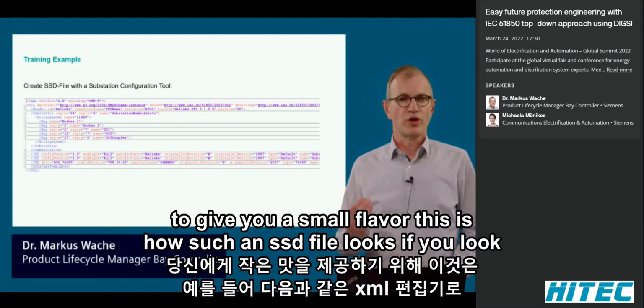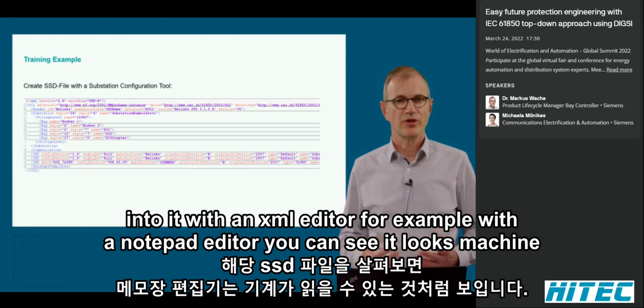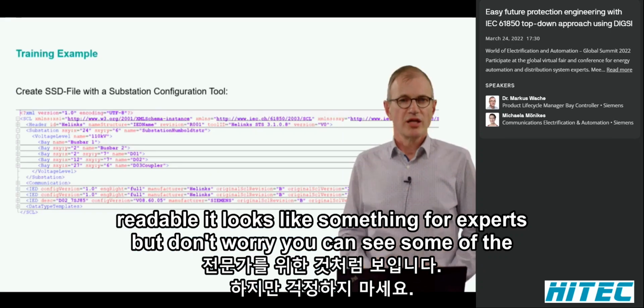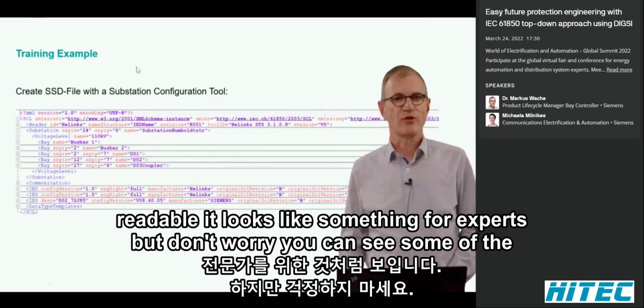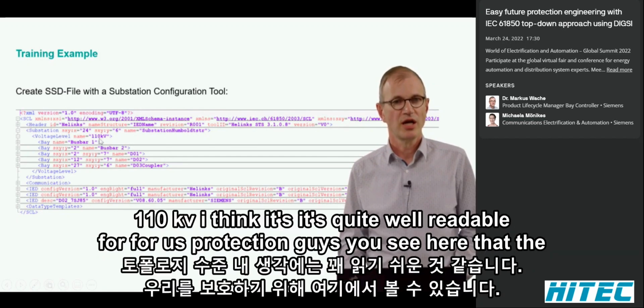To give you a small flavor, this is how such an SSD file looks. If you look into it with an XML editor, for example with a Notepad editor, you can see it looks machine readable. It looks like something for experts, but don't worry, you can see some of the parts which I mentioned here. You see the substation, the topology level with the voltage level, 110 kV. I think it's quite well readable for us protection guys.